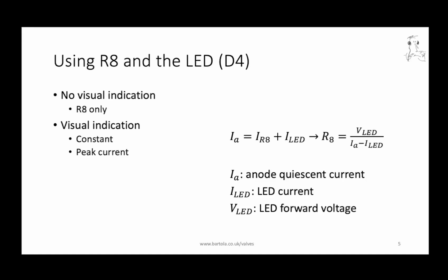For example, if you have the board as part of a driver that is managing a transmitting valve in A2 operation. So when the amplifier is being pushed into A2 mode, there is going to be current flowing from the hybrid mu follower into the grid of the output valve, and you want to visualize this, and this is something you can do as well.